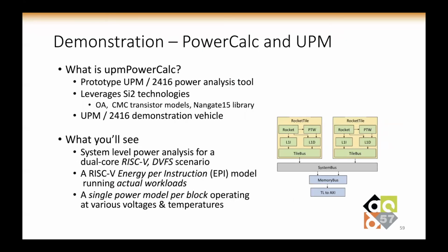So the demo will run our tool called UPM PowerCalc, which is a UPM-compatible power analysis tool developed at SI2 to be a demonstration vehicle for UPM. What you'll see in this demo is a single power analysis run for a DVFS system utilizing an energy per instruction power model of the RISC-V. A single power model will be used for all the various voltage, frequency, and temperature conditions.